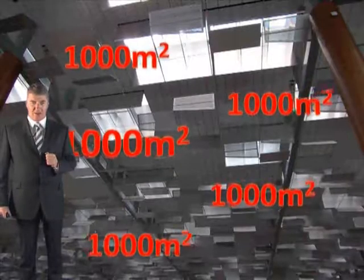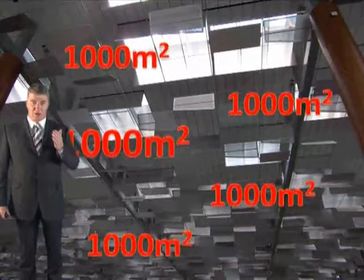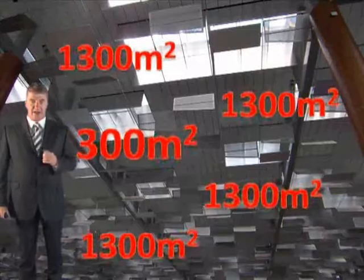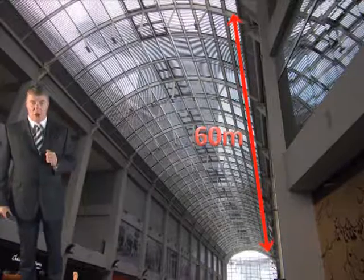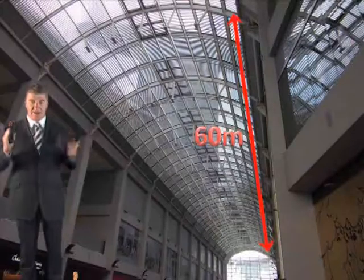However, in the UK, we have amended these reservoir sizes for shopping malls. So you've got to remember, if it's a shopping mall, there are different sizes. In a shopping mall, smoke from shop units is generally limited to 1,000 square metres in plan area, and this can enter an area with a reservoir with a maximum size of 1,000 square metres. Now, both of these can be increased to 1,300 square metres for mechanical. So what they've done is they've halved the values. Now, another common limit that you've got to make sure you apply is the maximum length limit. No dimension should be more than 60 metres, which is measured along the midline of the reservoir. So it can't be more than 60 metres long.